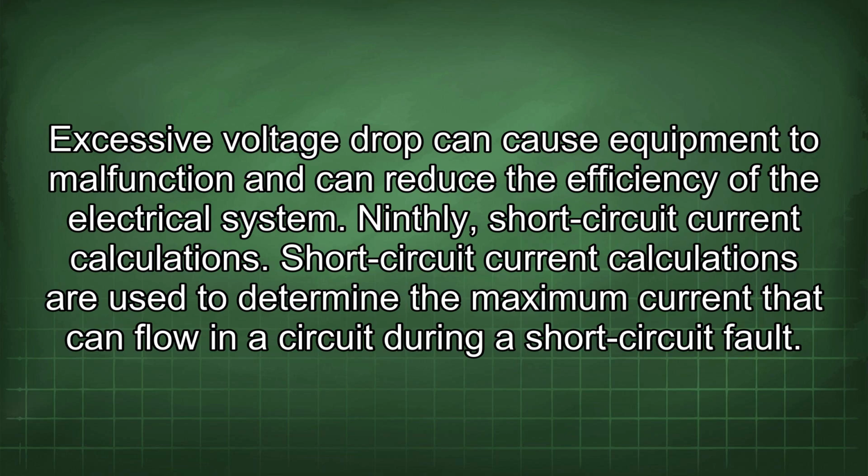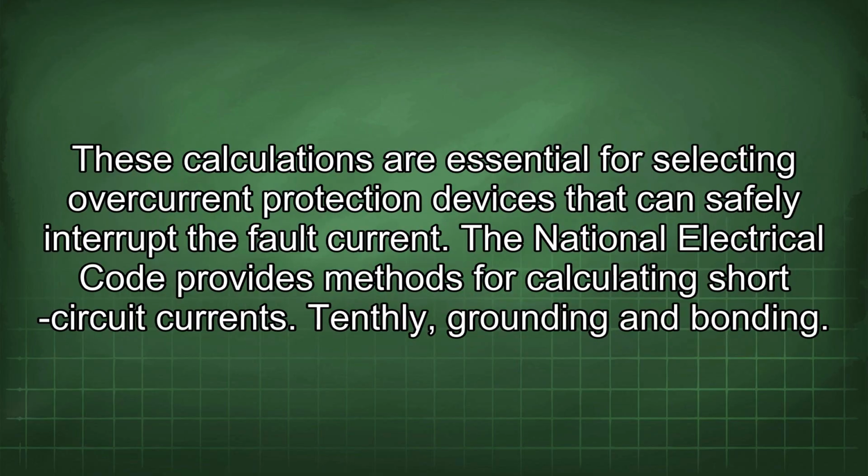Ninthly, short-circuit current calculations. Short-circuit current calculations are used to determine the maximum current that can flow in a circuit during a short-circuit fault. These calculations are essential for selecting overcurrent protection devices that can safely interrupt the fault current. The National Electrical Code provides methods for calculating short-circuit currents.